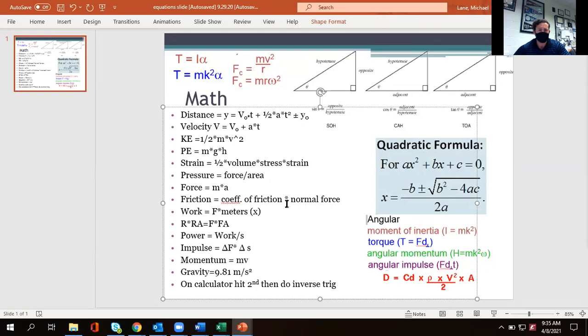Friction is going to equal the coefficient of friction multiplied by the normal force, and the normal force is the force that's going straight down into that object. If we happen to be working with something that is on a plane, the normal force is just that pen being pulled straight down. As I'm tilting it, it still has that force going down, but now it's the force going down into the platform. And we now have part of that force vector that's pulling the pen laterally. So at some point, the pen naturally is going to slide. It's actually stuck on that thing.